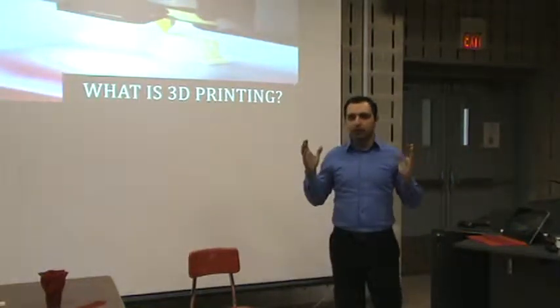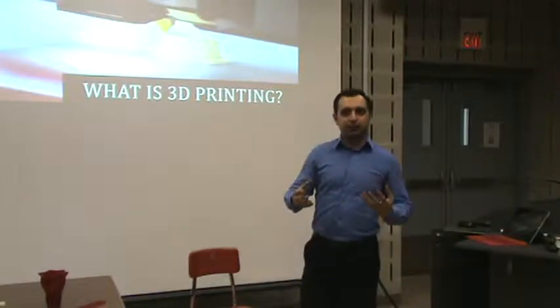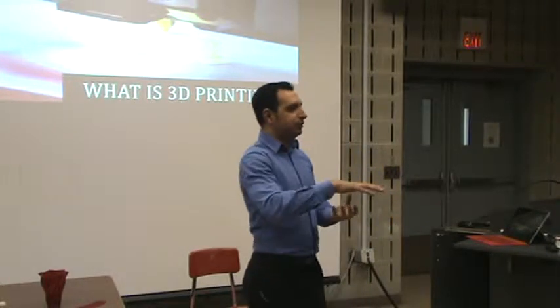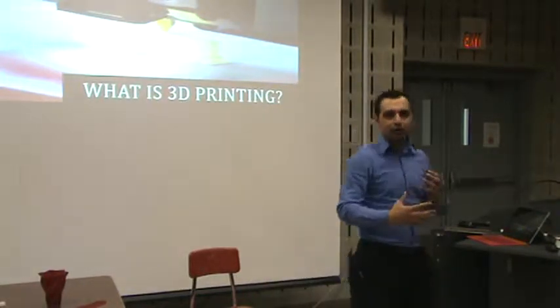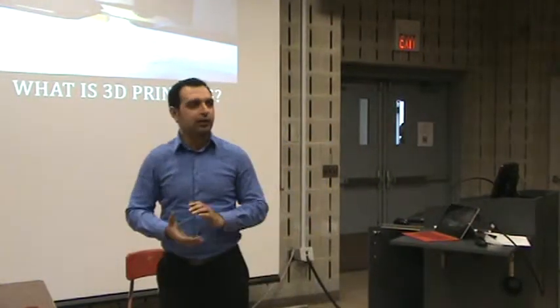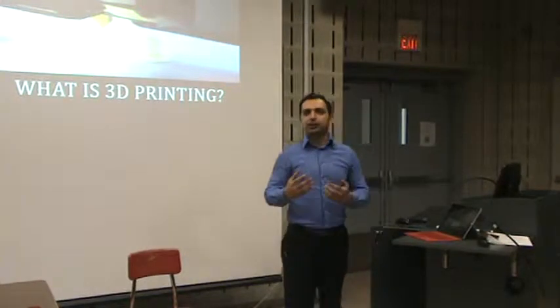So those of you who are from an engineering background would know that if you want to duplicate a part, you make a cast of it. First you put it in a box, you put clay around it, you make a mold, and then you pour molten cast iron or something to duplicate the part. Alright, that is fine, but there are problems with that. It's not a smooth finish and everything.